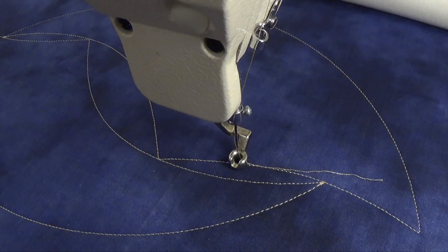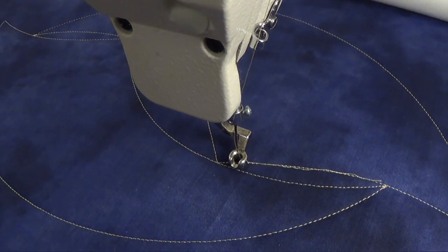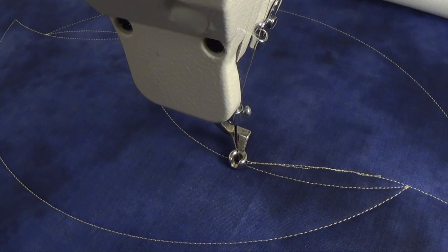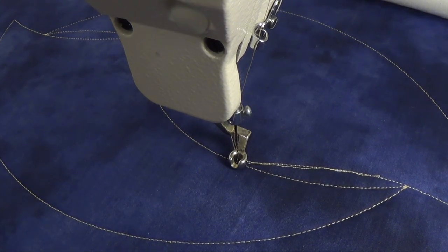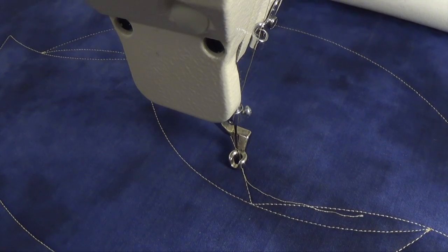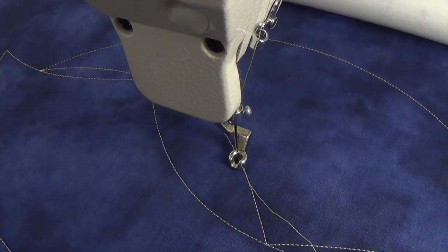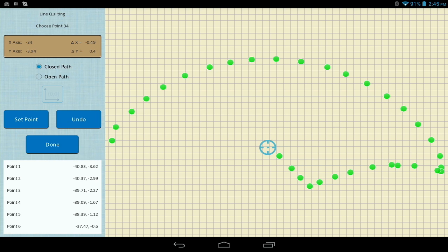Here, I'm just choosing maybe 1/2 to 3/4 of an inch between each point. And I'm making sure to get each point where it's an inflection point or a sharp change. We want to get those captured as well, so that we don't sand off those corners. We want to keep it well defined. So we just go around our area here.